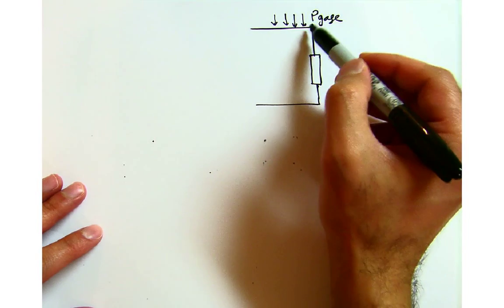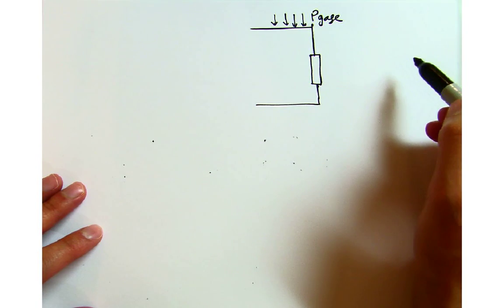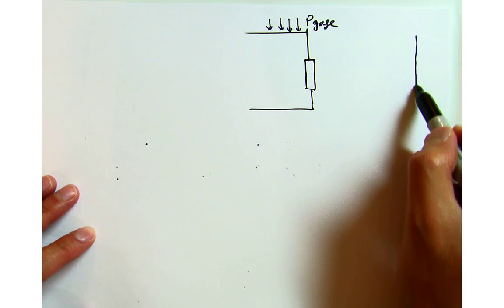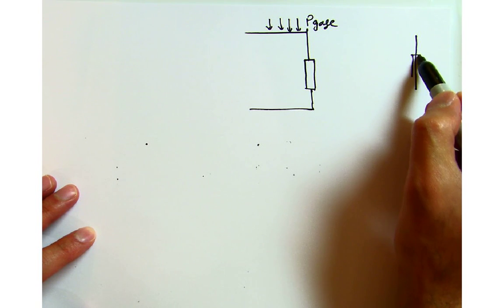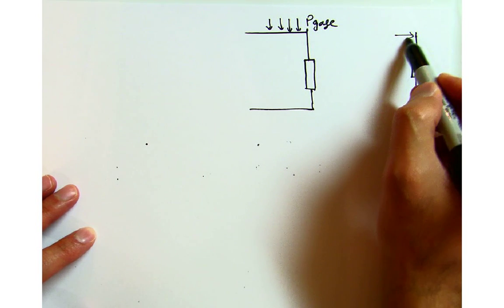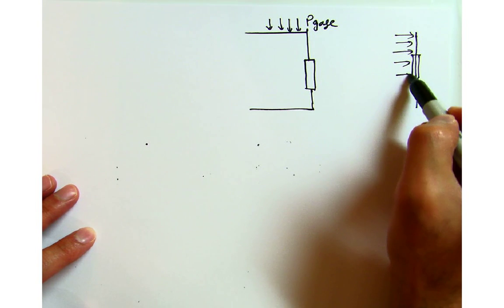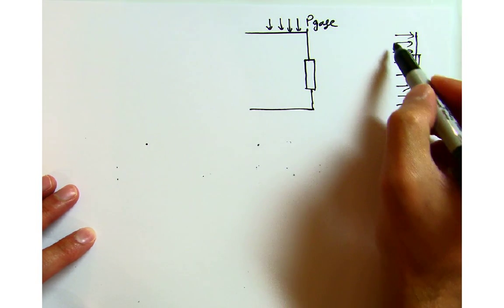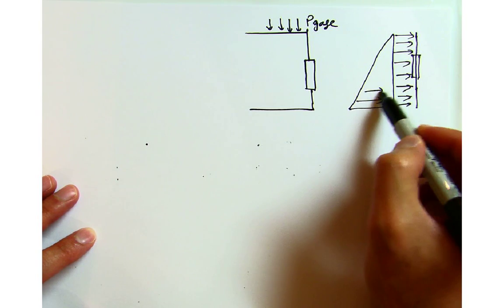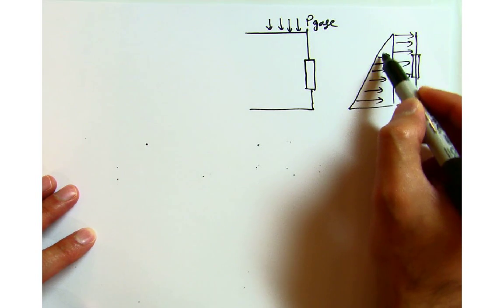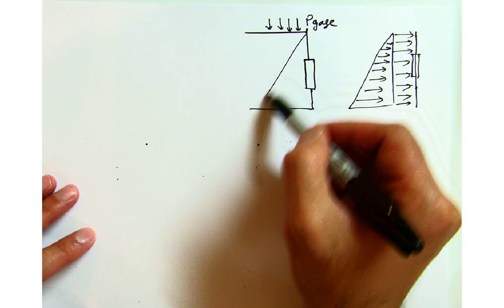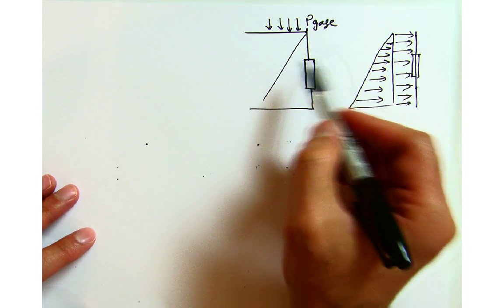Okay, and we also have the hydrostatic pressure. So the pressure distribution for this will look something like this. So you have this gate over here. The gauge pressure will be evenly distributed, and that's how it's going to look. And then after that you have this hydrostatic pressure, which is going to change linearly. Again, I can represent it over here. So you have a gauge pressure and so on.